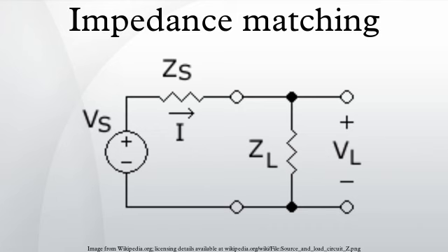Transmission lines. Impedance bridging is unsuitable for RF connections, because it causes power to be reflected back to the source from the boundary between the high and the low impedances. The reflection creates a standing wave if there is reflection at both ends of the transmission line, which leads to further power waste and may cause frequency-dependent loss. In these systems, impedance matching is desirable.